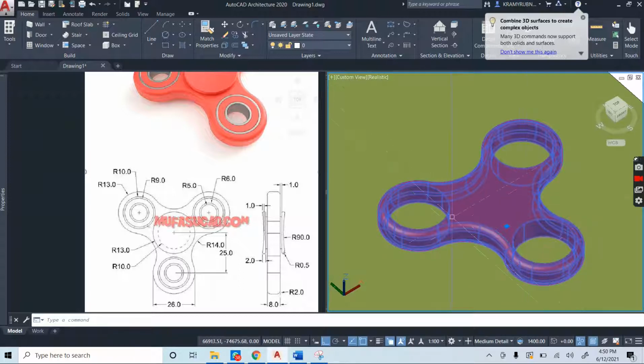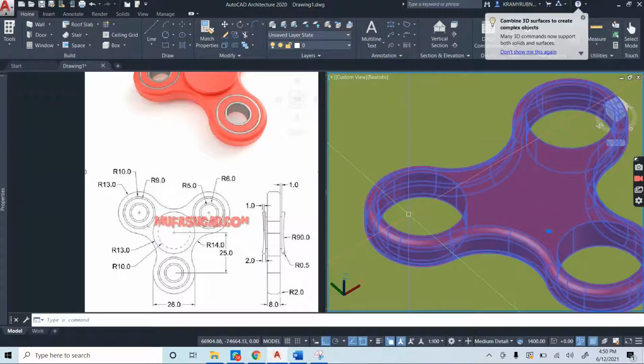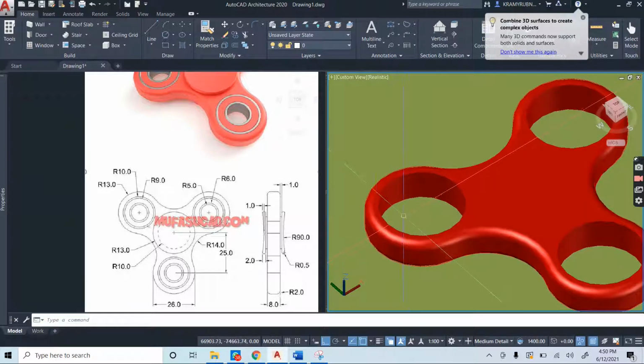Alright, but like I said, I'm also going to be giving the inner edges a fillet radius of 0.1. So let us go fillet with a radius of 0.1. Enter. Let's also do that in the multiples, because we're going to be filleting this edge.